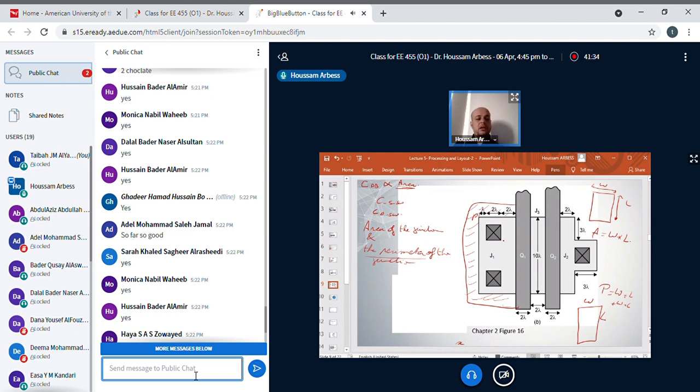That's why, yes, correct, Monica, here I need to calculate only this distance for J1. For J3, only here. For J2, this one is the perimeter that I need to calculate. Okay? Did you understand? Always you have to remove the channel side from the calculation of the perimeter. Keep it in mind. You have to memorize it. Once I need to calculate the perimeter of the junction, I need to remove the channel side from my calculation.